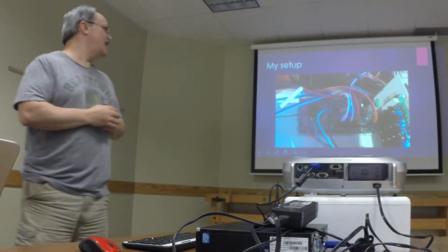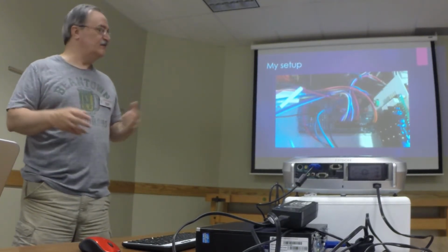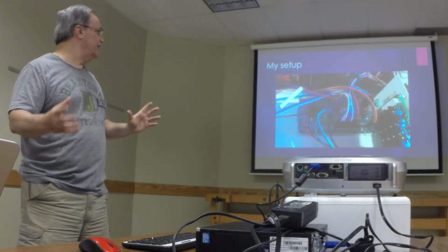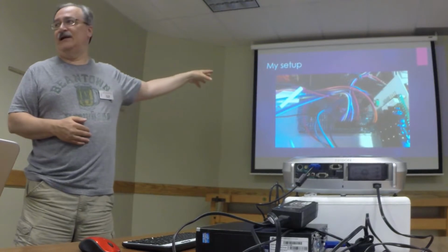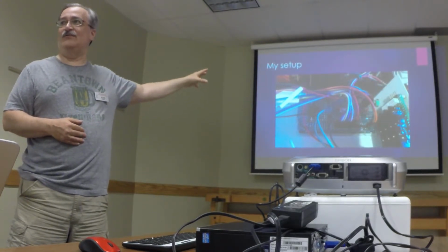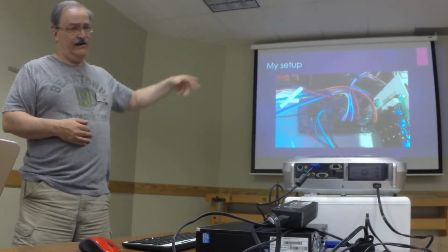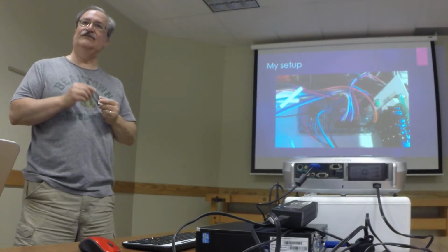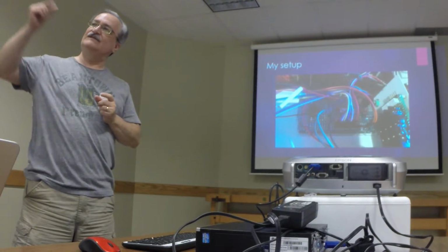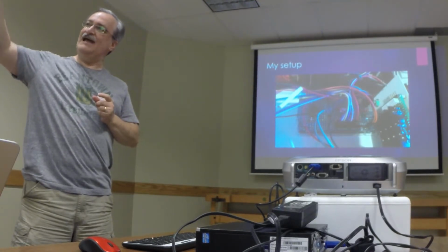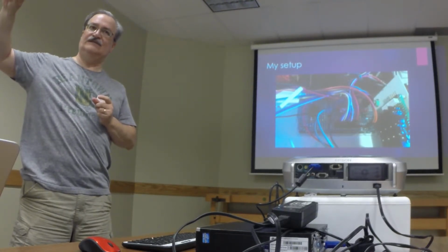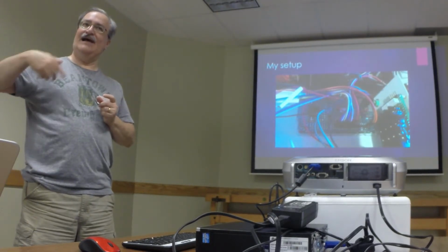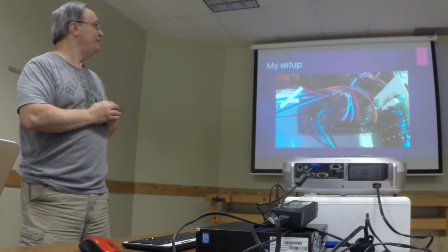The inside of the box, I would have brought it, but I had so much other stuff to bring, I didn't feel like hauling it in. But that's an Arduino Mega, so it's a little bit bigger Arduino board. It has more I/Os is the main thing. And because I was originally using an Arduino Nano as a remote unit, I had to have at least 2 serial ports, and you get 4 on a Mega. So I had to have enough serial ports for that.